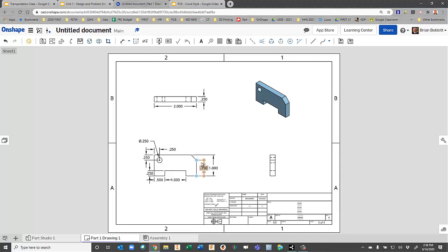Now the chamfer here, that lets me know from here to here is 0.75. But one thing I don't know that I really should know is how far it is from the edge to this corner. So I'm going to cheat a little bit and drag this 2.0 down. And I'll take my dimension tool and go from here to the solid line and say that's 1.75. So now I know for a fact how far that is. And that's kind of a big deal, because that lets whoever, either the builder or me as the designer, know exactly what that chamfer number is.